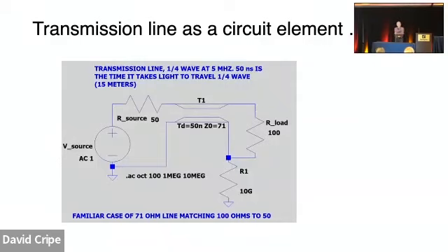I forgot to say this, and it's important, on units, SPICE is case insensitive. So 10M lowercase is 10 milli, it could be volts in this case, or cycles, and 10 capital M is also 10 millivolts or whatever. So if you want mega, you need to type MEG or you type E6 or something like that to tell it you want mega, because you'll end up asking yourself, what the heck's wrong here?